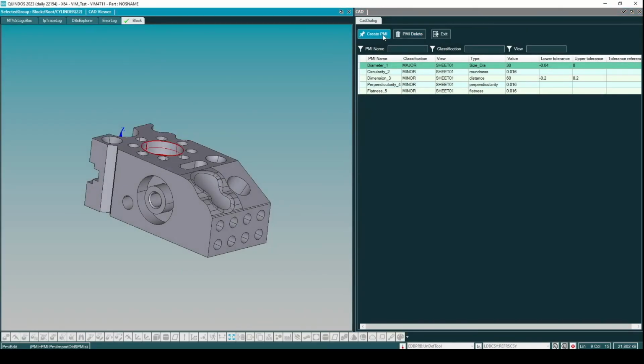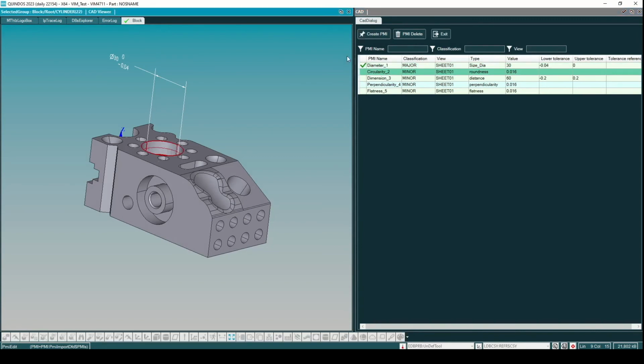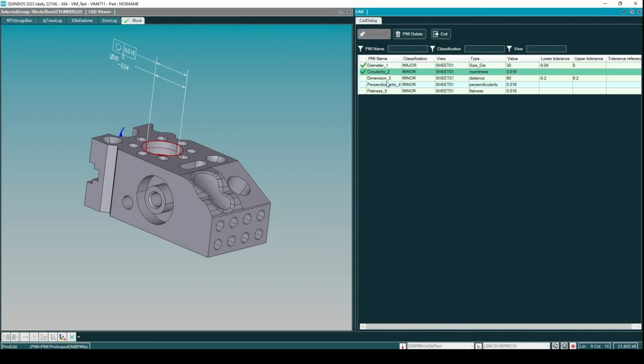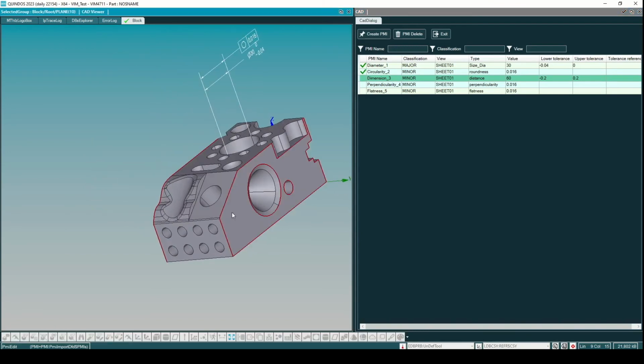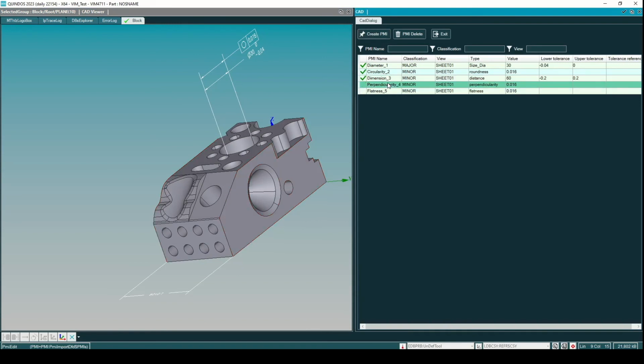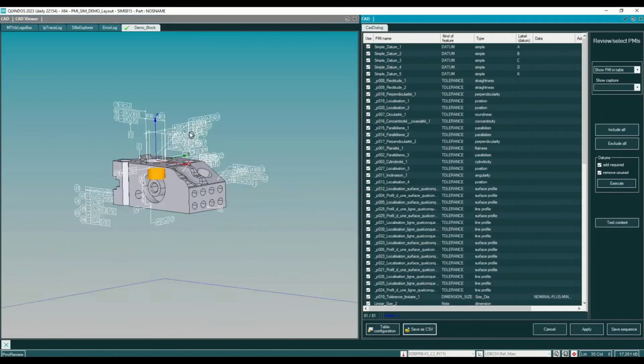Next, another example for the legacy data are the statistical export files. There are some DFD or DFQ files everywhere, and you can use these files to generate your own PMIs, like with the OCR. Sometimes you can export DFD files directly from your CAD system, or you already have DFQ files from older measurement programs. You will provide this information again as a list of PMIs, and then you can arrange them with a surface.